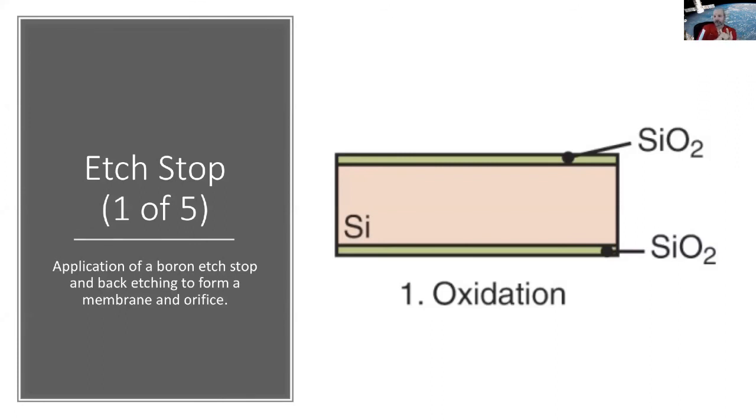Or you can put what's called a spin-on dopant and then put it in a furnace and anneal it, right? And then it'll diffuse. So when you learn about diffusion and fluidics and that kind of thing in your upper classes, you'll get the idea. So you can put a material in, heat it up, and it'll diffuse into the crystal. And as a result of that dopant, you can stop etches right away. It changes the surface chemistry once the etching gets to that point, and the reaction cannot occur anymore. So that's called an etch stop.